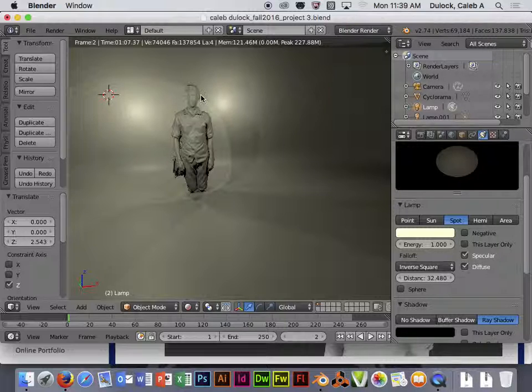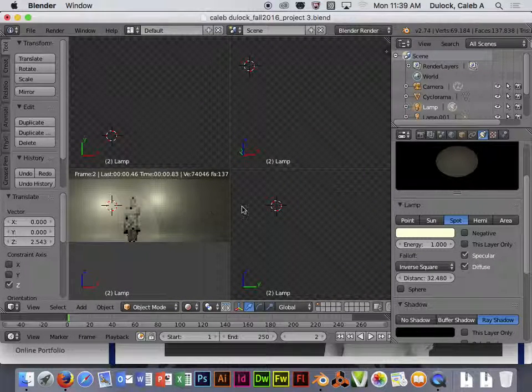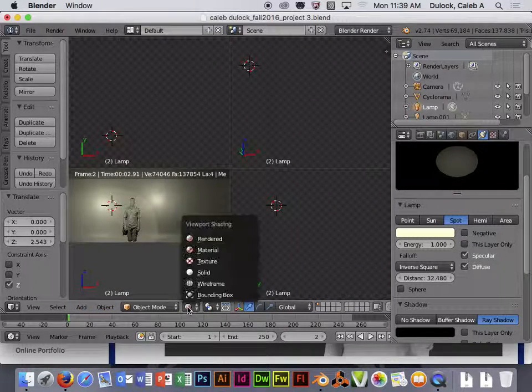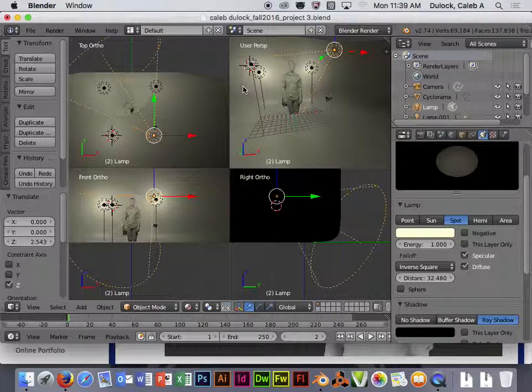So that's basically playing around with lights. Again, working with them in here, it's important that you are balancing out use of lighting, multiple lights, playing around with their properties in the property panel, and using your different four-angle viewport to really move things around accurately. For a lot of stuff that we do in here, using those four-port windows can be huge for accurately repositioning things.